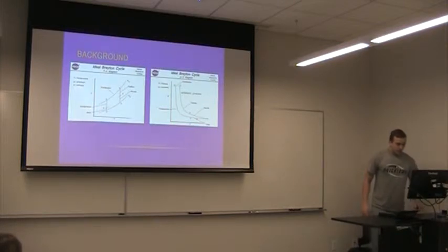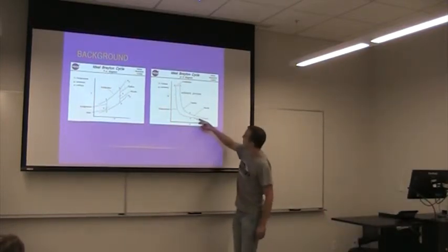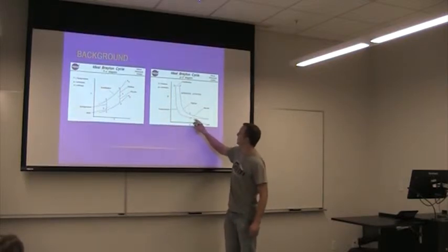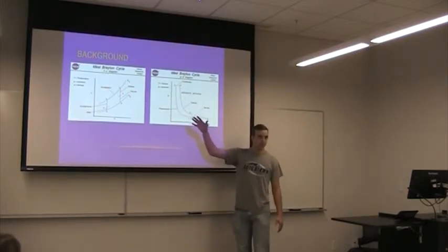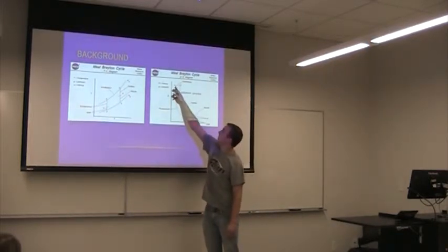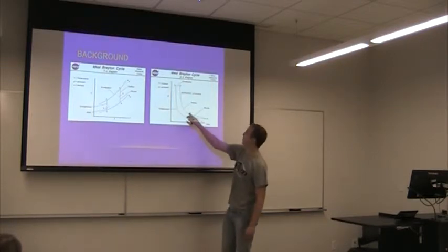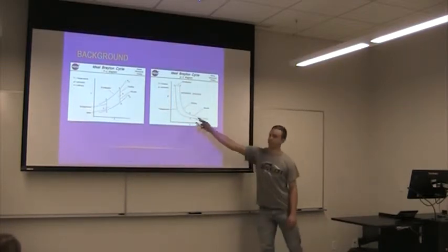The other one is the PV diagram. It just shows again the pressure increases slightly from 0 to 2. That's just air hitting the engine itself. Then from 2 to 3 is inside the compressor. No pressure change in the combustion chamber. And then the turbine loses pressure, loses pressure through the nozzle and starts over again.